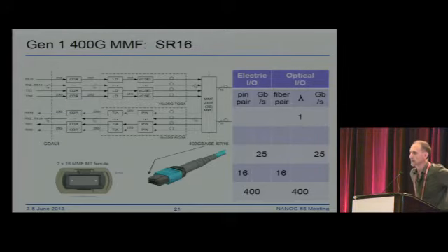I'm showing you a new connector, which is 2 by 16. All these MPO parallel fiber connectors that you use to run bulk links across the data center have been by 12. The by 12 is a historical artifact from when people would efficiently pack copper cables. It's sort of like stacking oranges. But we're trying to move to by 16. So this connector was developed by US Connect, and you'll see that for 400G.